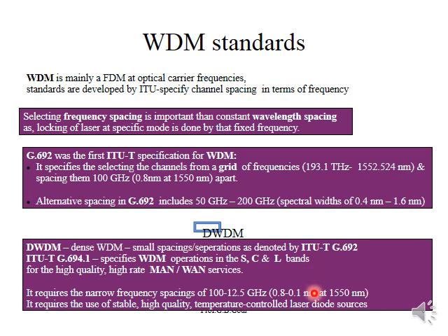This can be supported with temperature controlled coherent laser diode sources. Temperature is controlled because heat is generated. To generate coherent light sources with a unique wavelength, heat is generated, so more stable diode sources or optical sources are required. So the main features you remember: it operates over the S and L bands, you remember its frequency ranges, it needs temperature controlled laser devices, and it is applicable to MAN and WAN services.